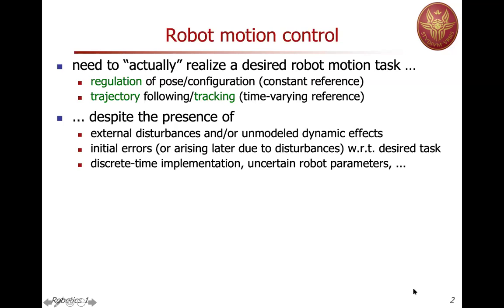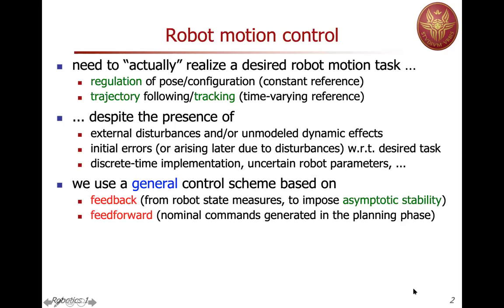And finally, you may have a discrete time implementation, and this is what happens in our case, in our experiment. And this will delay your commands, and you will keep also velocity constant for an interval which is too long. You should have updated this velocity at a faster rate, possibly continuously, which is impossible, in fact. And this will drift you away from the trajectory. This is why you need control, you need feedback, okay?